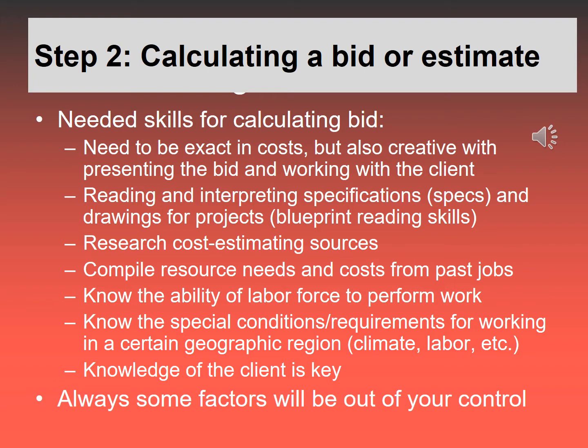You would at least have some of that information from the first job about how long each panel took, how long each hole took to dig, how much concrete was used for each hole, and you can just use that kind of as a multiplier for the next job. So that's the best way to really understand and do good, accurate cost estimations. There's always going to be some things that you don't know about, so you do usually have to include contingency costs, build them into your estimate, things that come up that you couldn't plan for.